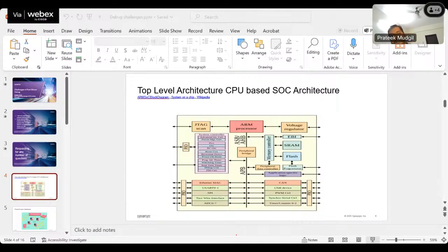So I was looking at the topics which we have covered in the past. People have discussed ATPG and test patterns and these things, right? The problem is that ATPG and these test patterns work majorly on the digital blocks. An analog block doesn't give you access for putting in scan chains and these things, right? So it again becomes a challenge where the analog block is not allowing you to put in the scan chains, and then if there is some fabrication issue itself on the physical layer, right?